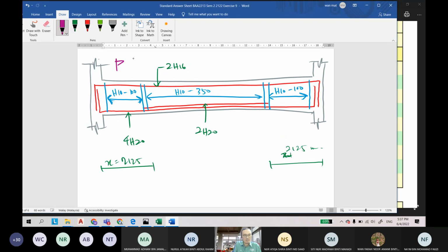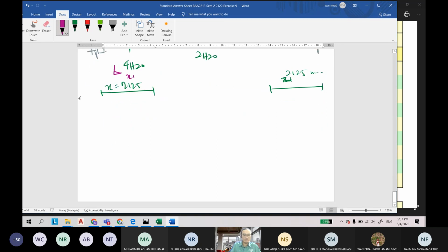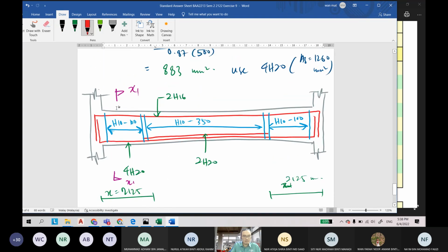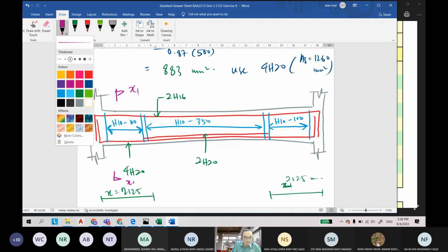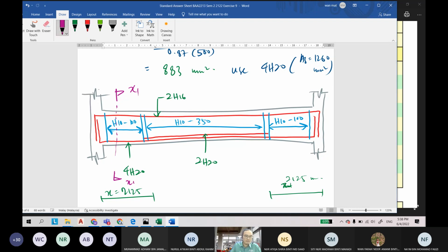So if you have two different cross sections, let's say this is x1 to x1, near the support you have your design like this one. This is the cross section x1 to x1. You have the top reinforcement here. You imagine that you cut this section.